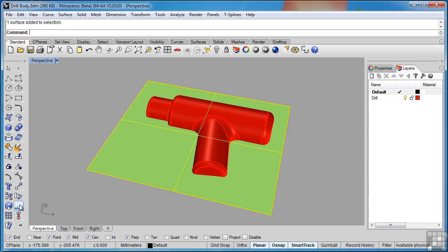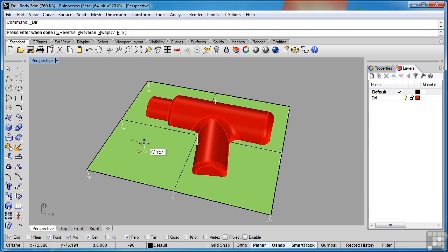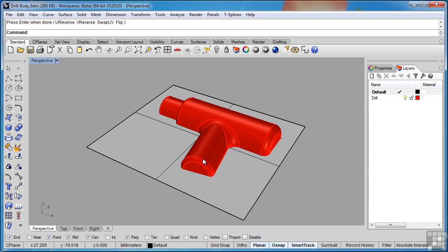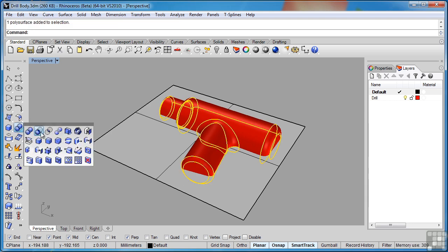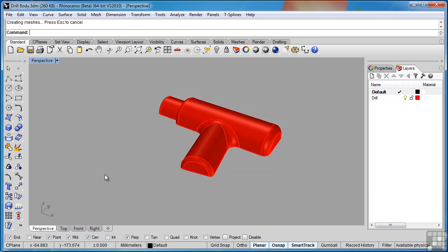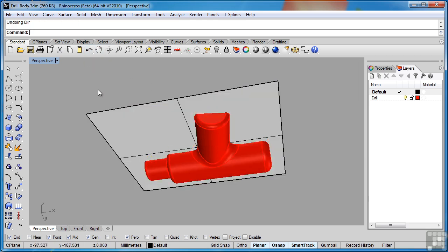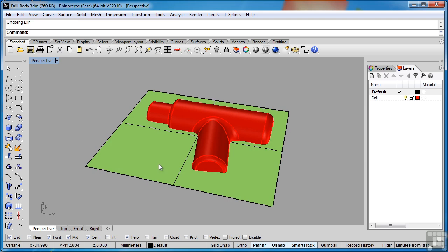So if I were to take this and using the Analyze Direction command, flip this, so that now this is the front side, and this has the green applied. So if I select this, do a Boolean difference using this, now you can see this half remains and that portion is deleted. Go ahead and undo a few times and get that back so the normals are flipped.